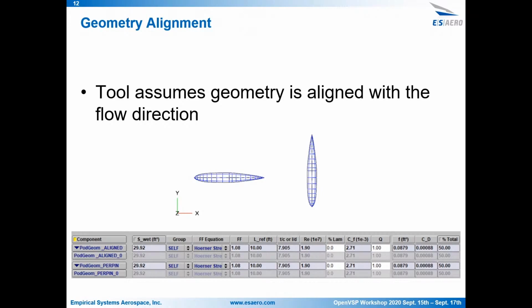For instance, if you are trying to do a landing gear strut, like a typical bent aluminum landing gear strut that's on a Cessna or something, modeling that with a wing component would work fairly well to align with the flow.